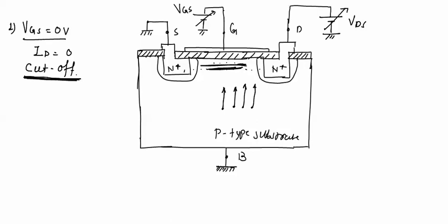In both the cases, we saw that when VGS equal to 0 volt, sufficiently large current was flowing, that is IDSS. But in case of enhancement type MOSFET, there is no channel between source and drain. So unless and until we apply proper gate to source voltage, there will be no channel and there will be no conduction. That is ID will be 0.